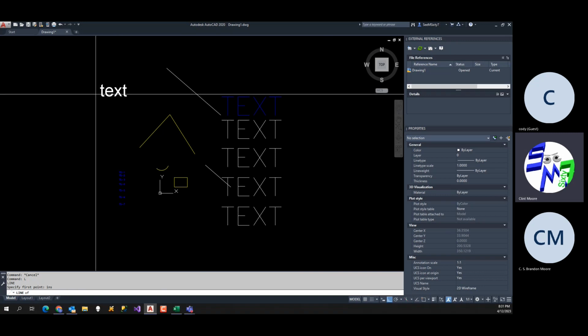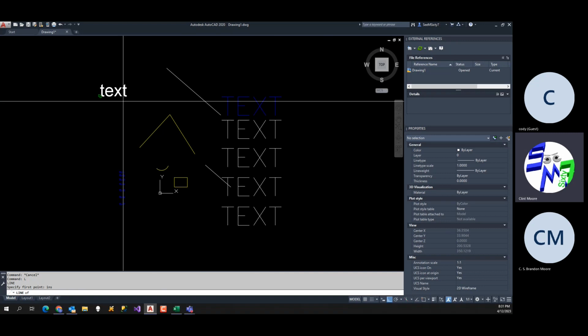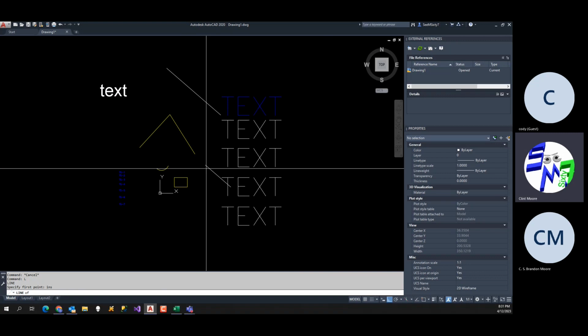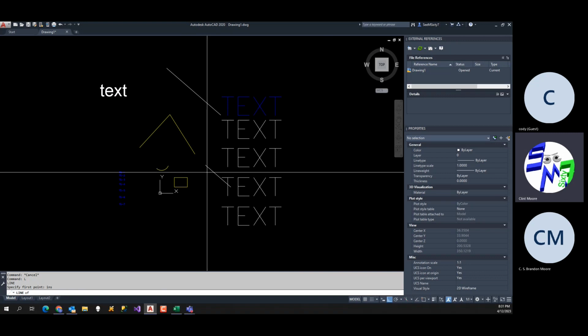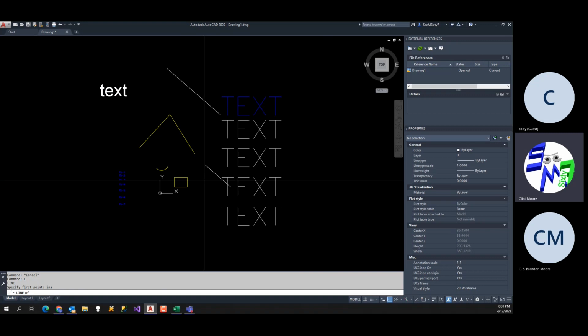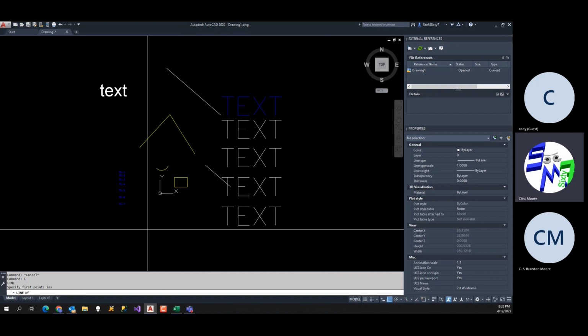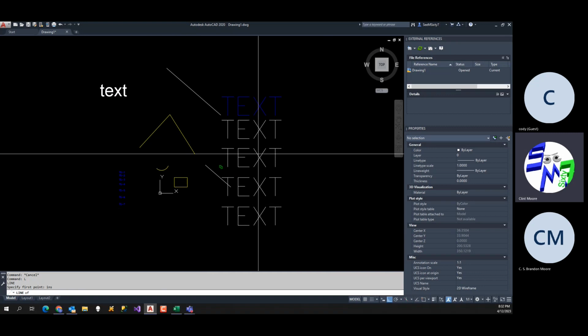So you'll find that I prefer to work with standard AutoCAD fonts instead of Arial. But there is a benefit to using Arial with a 1.0 width and a 0 rotation, because then it's easily recognized in an Adobe, in a PDF format, as actually recognizable text, versus you have to do OCR on a PDF that's actually created from AutoCAD, unless they cheat and use the PDF SHX setting, which we will not get into right now, but that's another thing that actually creates a little more headache and a lot more overhead.